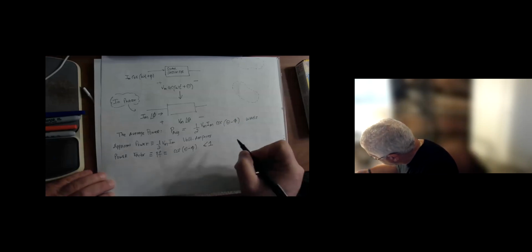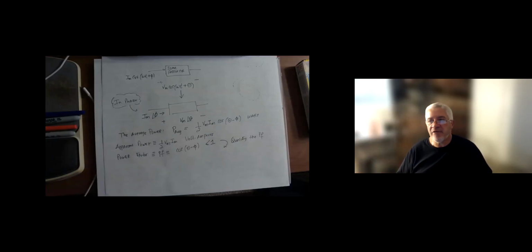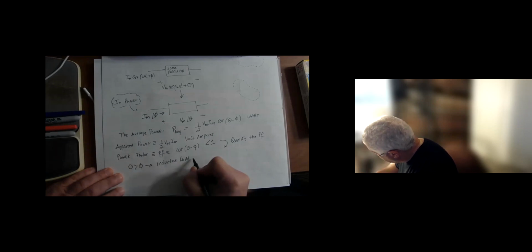And then finally, one of the things you have to remember is that you're going to be able to qualify the power factor, the PF. That is, when theta is greater than phi, this is an inductive load, and it also means that the power factor is lagging.